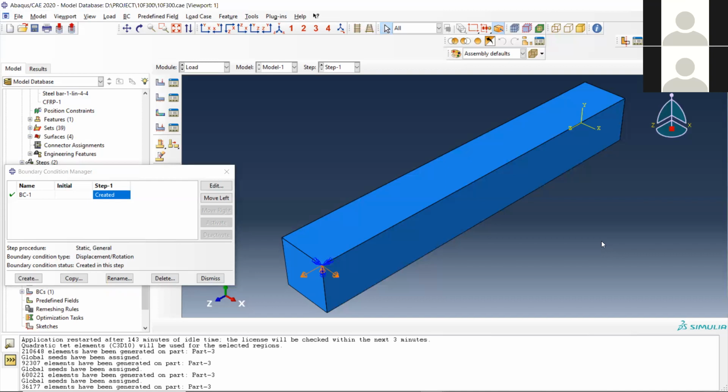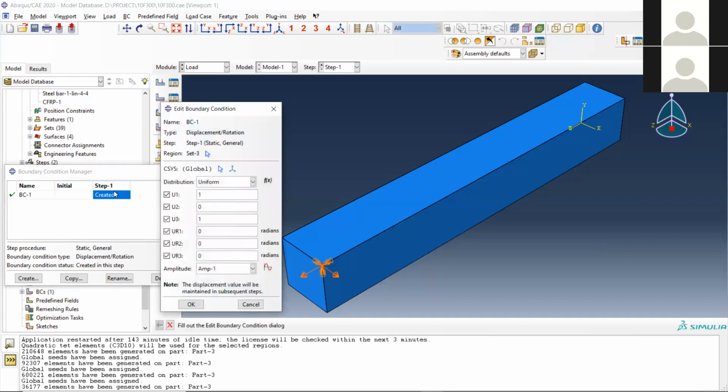Yes. But if I just want to apply the cyclic load only laterally? Yeah, that's what I'm trying to tell you. So in that particular case, you can do only the cyclic loading case once. And for the other one you should use only a static load case. It's a separate analysis that you have to do. Okay, sir.